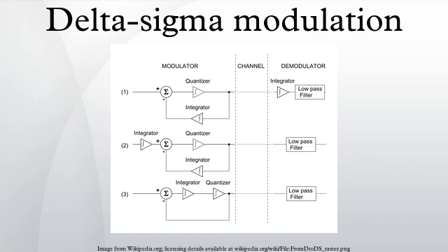The resultant effect is that the integral crosses the threshold more quickly on the right than on the left. A full analysis would show that in fact the interval between threshold crossings on the right is half that on the left. Thus the frequency of impulses is doubled. Hence the count increments at twice the speed on the right to that on the left, which is consistent with the input voltage being doubled.